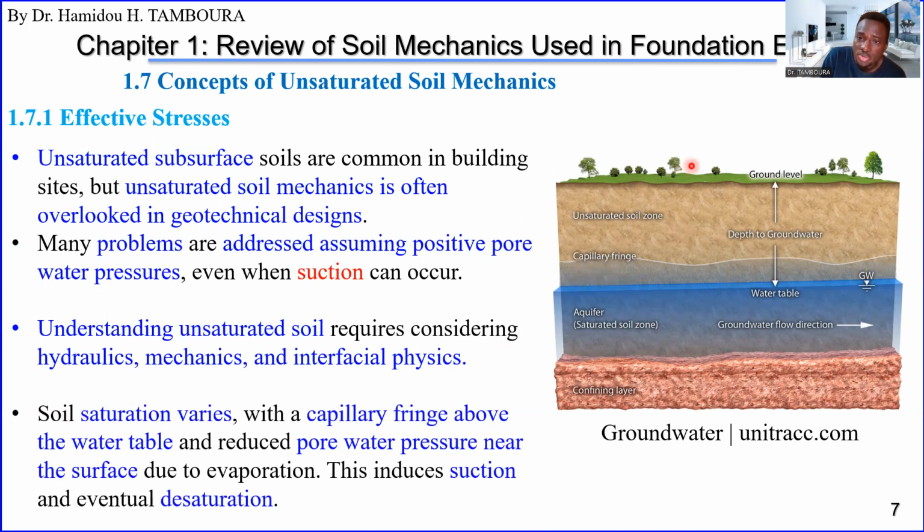So the saturation of this zone, the degree of saturation, will depend on this capillary fringe and will depend also on the pore water pressure, the decreasing pore water pressure when you get near to the surface, due to evaporation. So this will induce suction and eventually desaturation, meaning the degree of saturation will turn to zero.